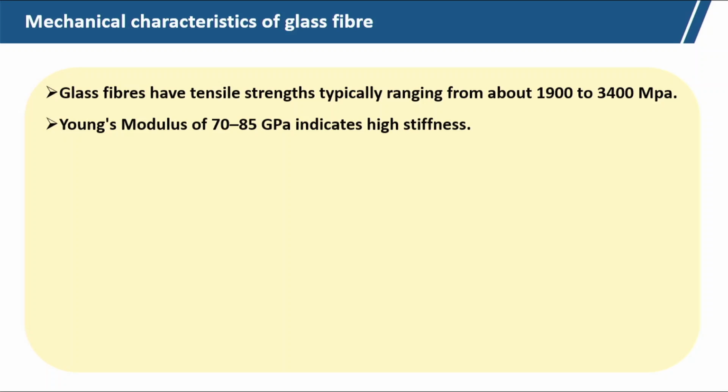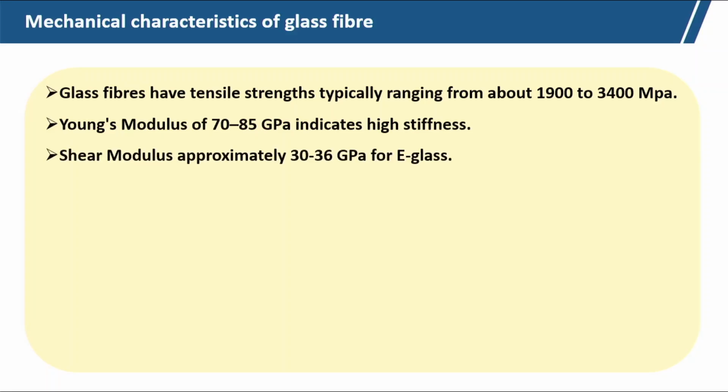Young's modulus is 70 to 85 gigapascal, indicating high stiffness. Shear modulus for E glass is 30 to 36 gigapascal.